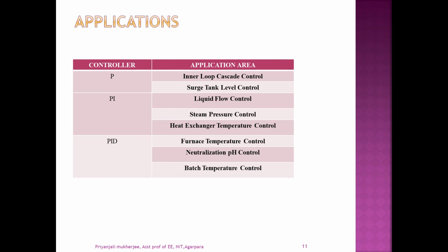Next, the applications of PID controller. One application is the furnace temperature control. It's commonplace for the material involved to have a large mass because the furnace typically involves heating and holding a large amount of raw material at a high temperature. And as a result, it possesses a high degree of inertia. The material's temperature does not change quickly even when the heat is applied. This characteristic results in a relatively steady process variable signal, and it allows the derivative term to effectively correct for the error without excessive changes to either the controller output or the final control element.